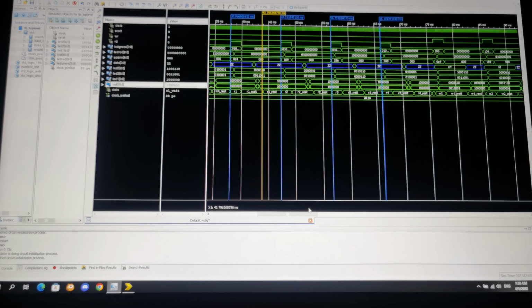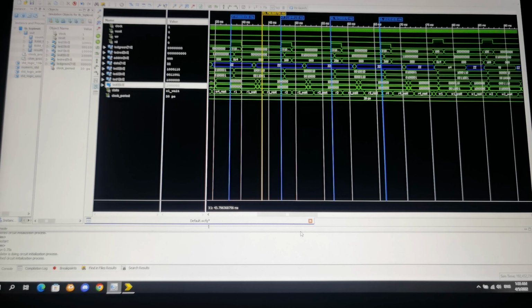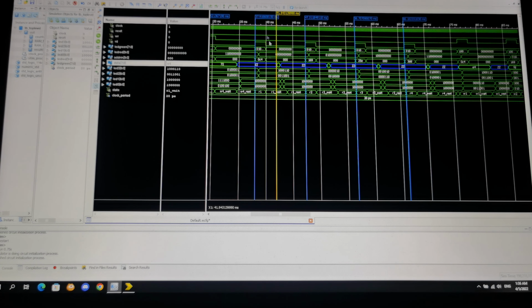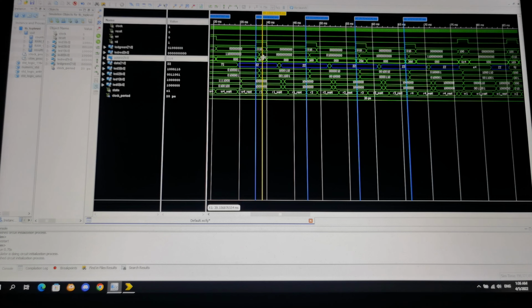Just like what I said just now, for the read operation, the signal RD will be set to 1 to run the operation, and the signal WR will be set to 0. This is the first read operation. It first enters memory bank 0, and then reads the memory data at memory address C4. Looking at the address input here, it shows the value 0 C4. This 0 means the first memory bank is being used, and C4 is the memory address we used to write on.